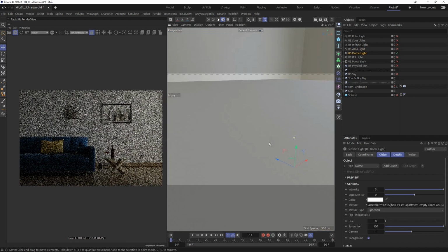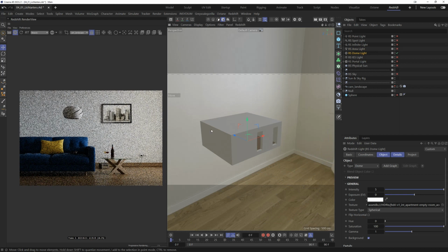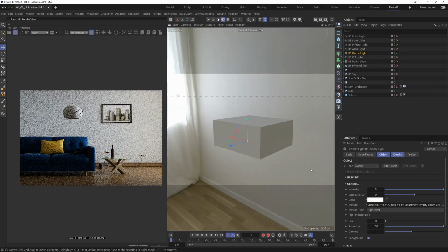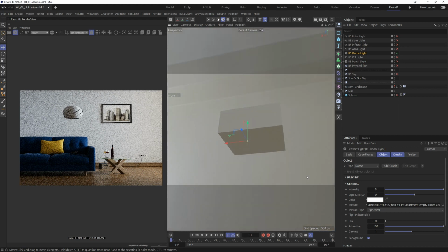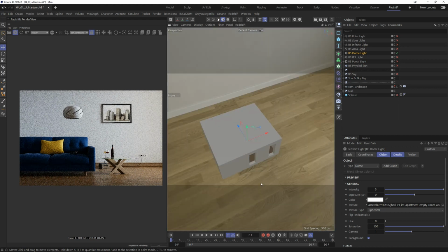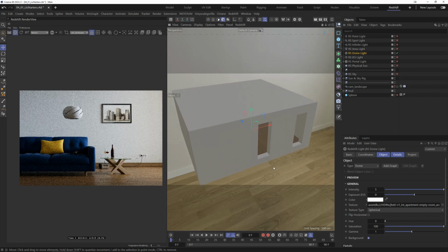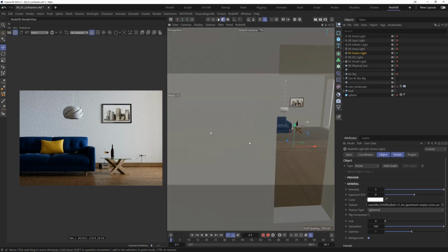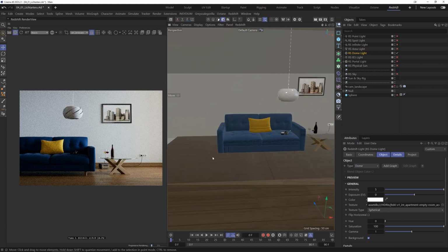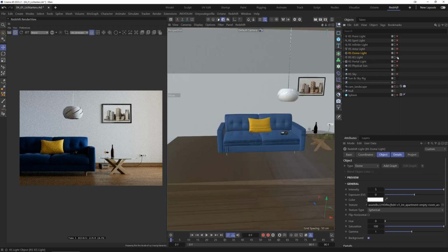This is the dome light. This is an ambient light that is also in an infinite space. This is a texture that wraps 360 degrees around our space. This light is also very commonly used for photorealistic renderings. We get the best results with this, with HDR textures that include multiple exposure levels. The higher the resolution and the more exposure levels such an HDR has, the better quality we achieve. At lower resolution, of course, the reflection looks correspondingly worse in geometry. I will go to the light and turn that off.